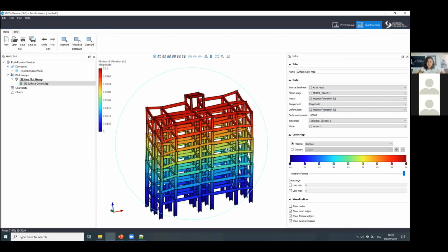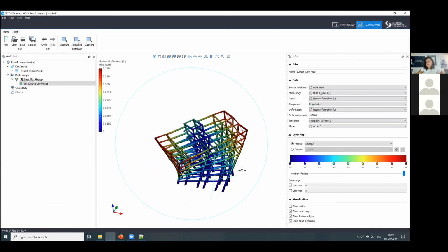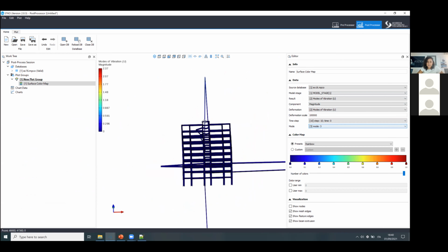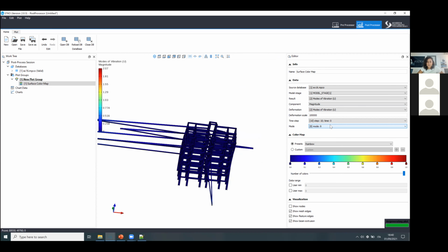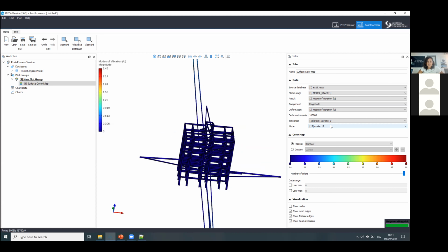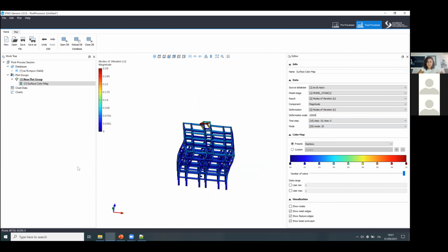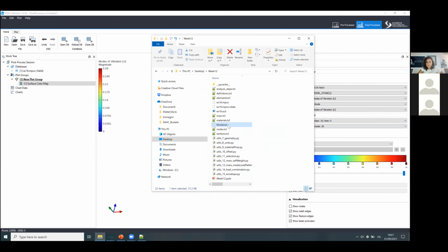This is something that I always suggest you guys do when you create a new model. First, run a linear elastic analysis with eigenvalue analysis. This happens because these are local modes, no problems. We don't care about this. Of course, I save the information for these modes here.